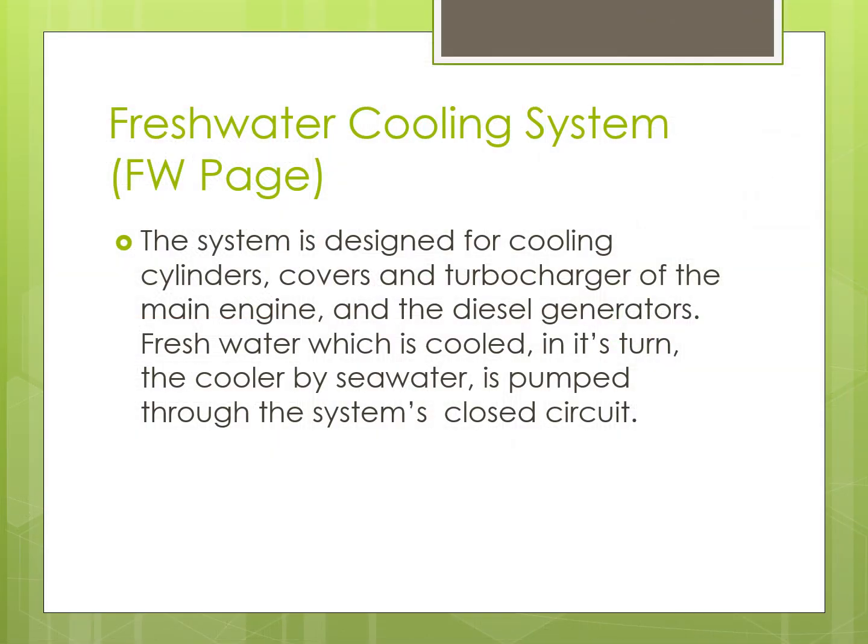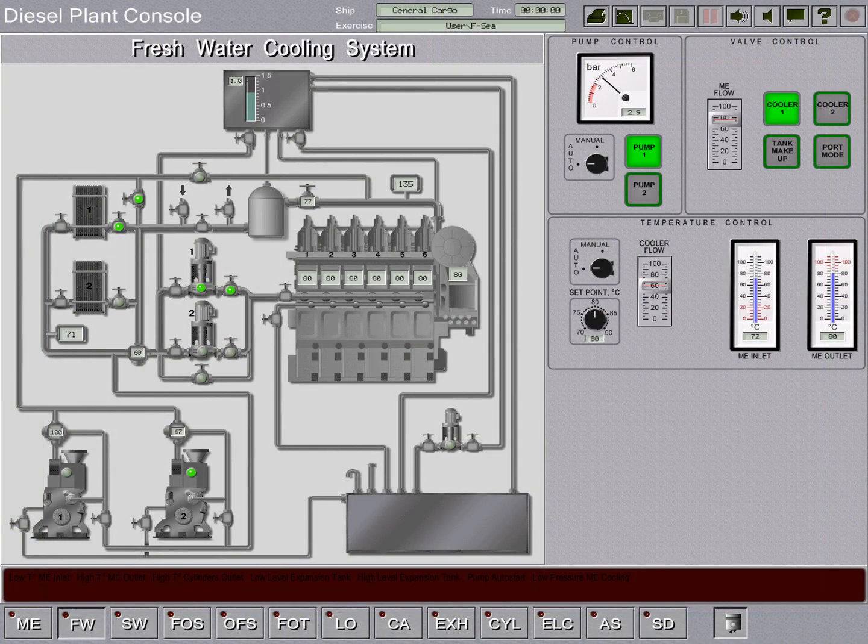Freshwater Cooling System. The system is designed for cooling cylinders, covers and turbocharger of the main engine and the diesel generators. Fresh water, which is cooled in its turn in the cooler by seawater, is pumped through the system's closed circuit. Freshwater Cooling System, FW page.